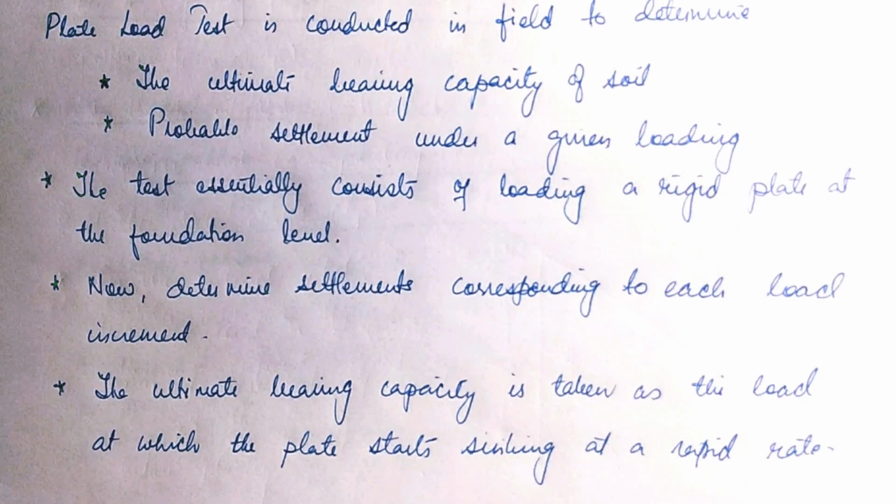The test essentially consists of loading a rigid plate at the foundation level and determining settlements corresponding to each load increment. The ultimate bearing capacity is taken as the load at which the plate starts sinking at a rapid rate.